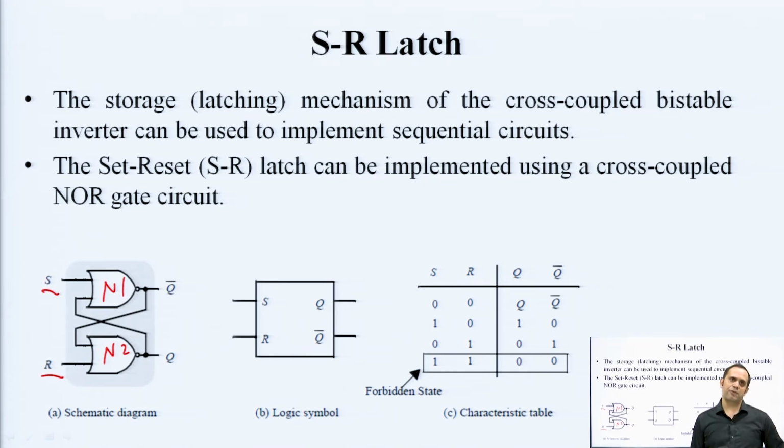Every flip flop and latch circuit generally gives you both the output and its complemented form also. This is the symbol: you have two inputs S and R, and two outputs Q and Q bar. Just note here that I have not added any clock or enable symbol as yet. There is no pin showing you a clock or enabling point as yet. I am just showing you the latching operation right now, so whatever you have as input, how it is being altered at the output.